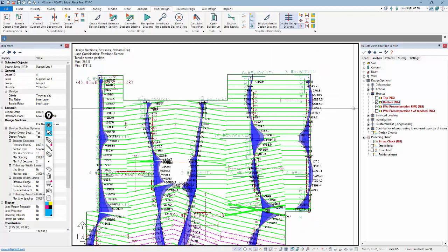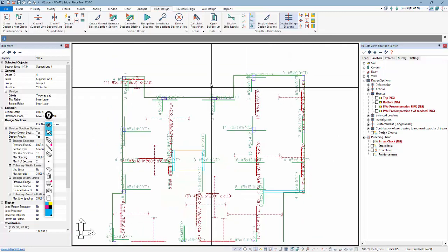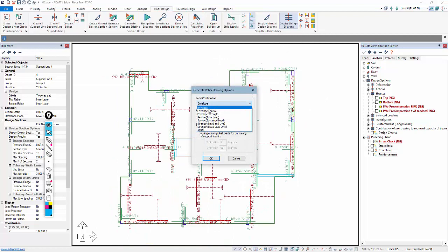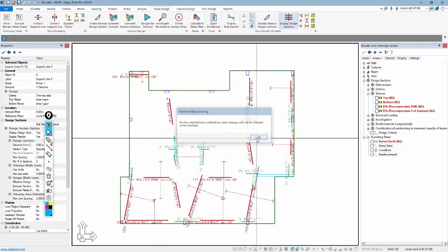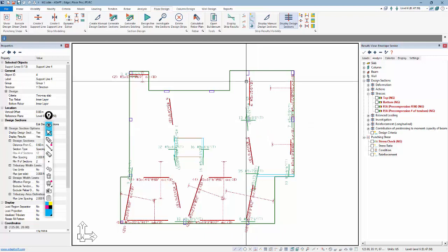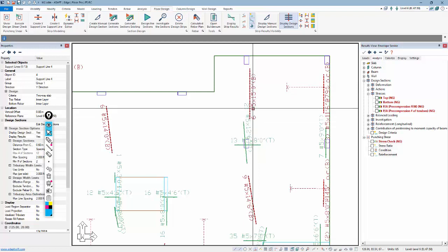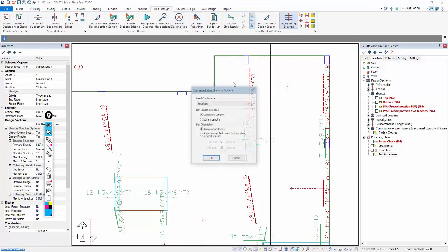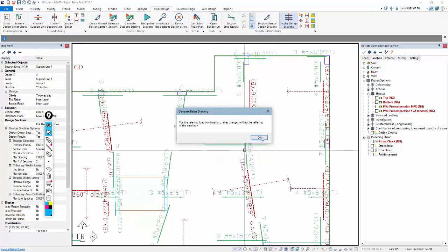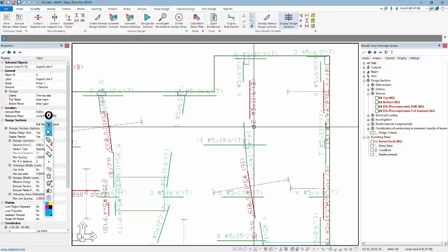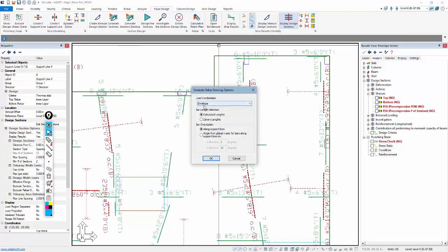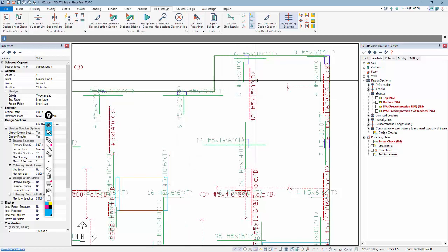So this is an output of the minimum reinforcement. If we go back and we look at the strength reinforcement, I'll just envelope strength instead of service. This now is the output of the strength reinforcement. And you can see there may be more bars for strength at the same position than there might be for service. Back to that example, for strength at this location, I need 6 number 5 bars. The tendons contribute quite a bit to the capacity of those sections. And if I go back and toggle that to service, envelope service, I need 12 number 5 bars. So service would control in that region. If I go ahead and just envelope everything, we're going to see 12 number 5 bars.